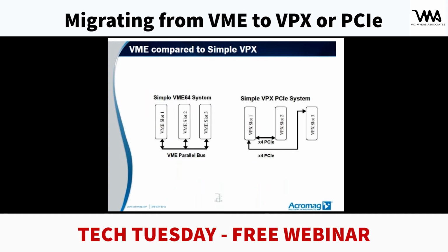In this illustration, there's a comparison here of a very simple VME 64 system as compared to a simple VPX PCI Express based system. On the left-hand side, you can see that there's 3 boards. They're all connected to each other through the VME, which is a parallel bus architecture. On the right-hand side, in a very simple architecture, you can see that there's 3 boards.